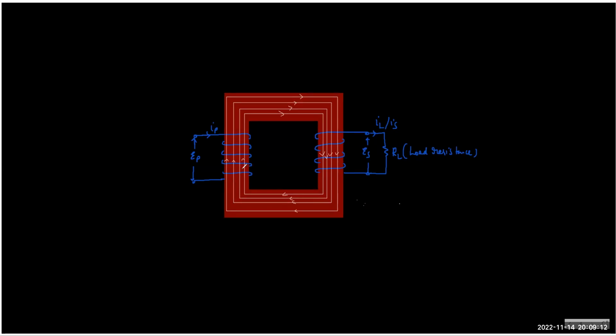Don't take this diagram strictly. This is just a matter of convenience of drawing. It may be a smooth turn, not a sharp turn. Now, we cannot guarantee that 100% of the lines of force will move through this path. Sometimes there is some leakage of lines of force. Some lines of force may go through air also. That is a small part, and such a situation is called flux leakage.